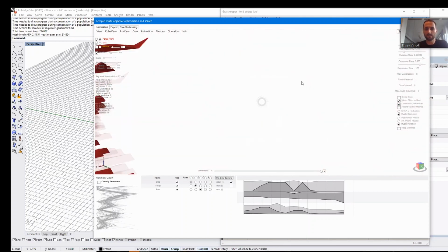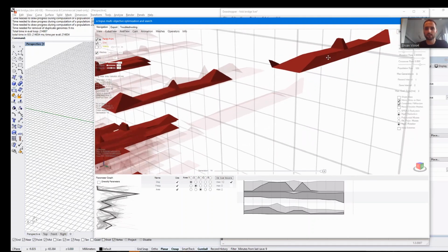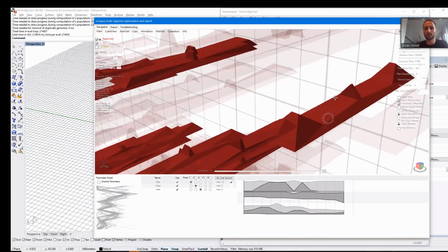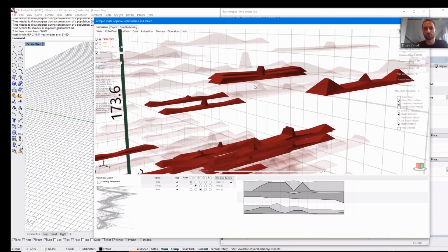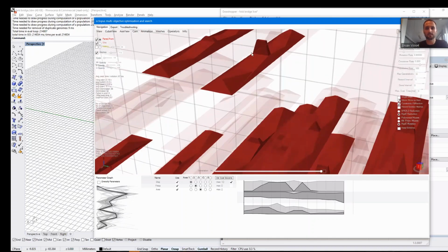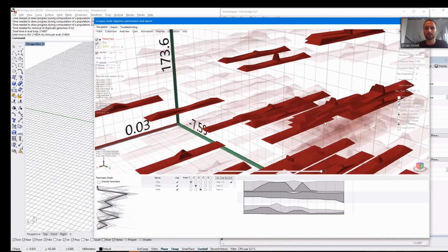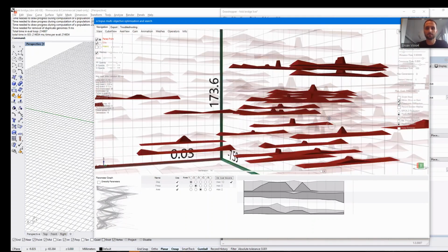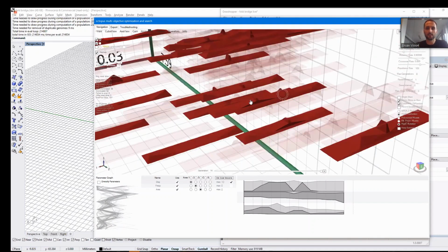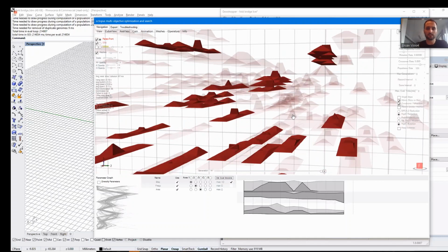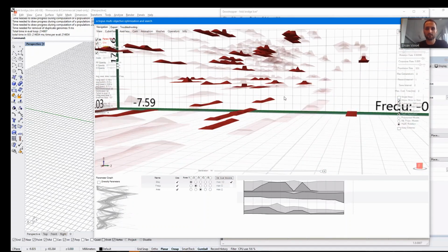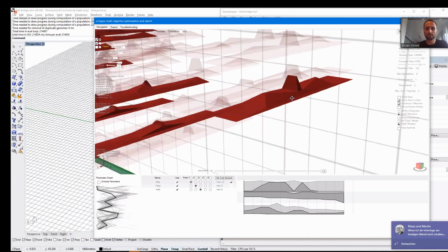The bump in the middle, I think, is mostly due to the fact that we loaded on 2 points, and the 2 points where it applies all the load should also be stiff in themselves locally. So it does this little stiffening of the loading area. That's why the little bump in the middle of the bridge comes up. And the other shapings, they are trying to create some kind of folding.